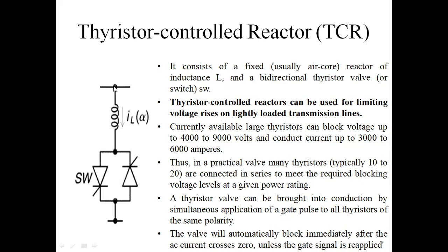This is the transmission line, and this thyristor-controlled reactor is connected in shunt, in parallel across the load. The TCR function is absorbing reactive power during light load hours.